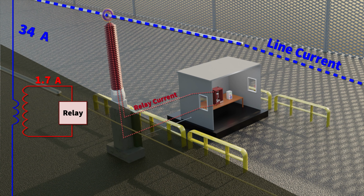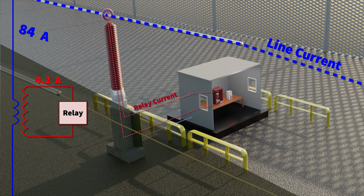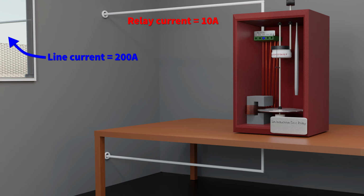But as you can see here, we know the line current because we know the CT ratio. So in this case, if 100 amps is flowing, we know that there's going to be 5 amps on the CT secondary. Inside the relay, let's take a look at what happens when we have a 200 amp line current and a 10 amp relay secondary current.